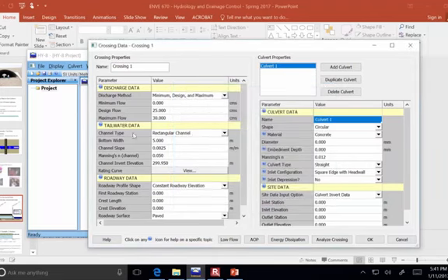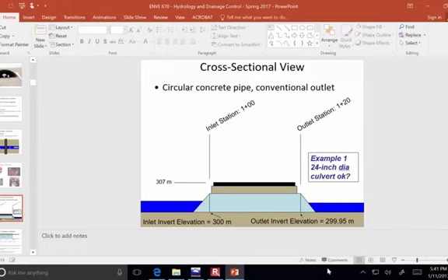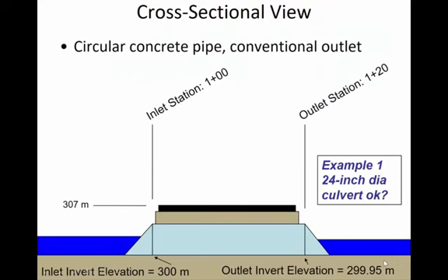All right, so that's the tailwater data. Now, the roadway data, it needs to know that information in case the water gets high enough that it starts flowing over the top of the culvert. Consider the worst case scenario: we didn't make our culvert big enough and the water keeps getting deeper and deeper and then it flows over the top.